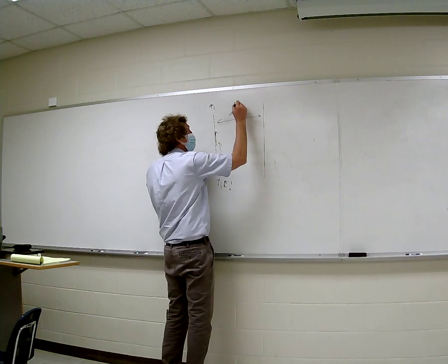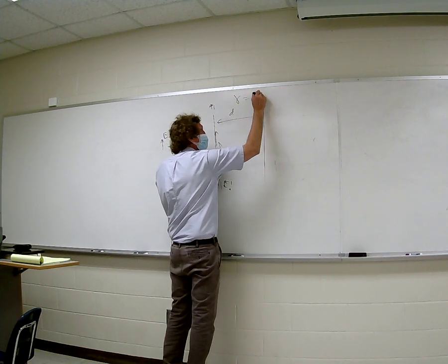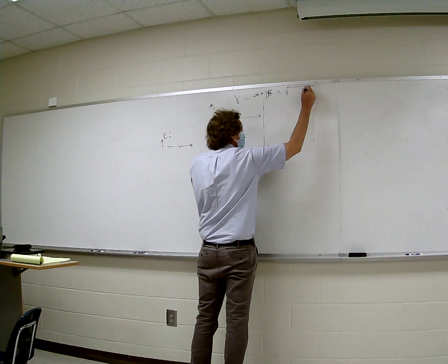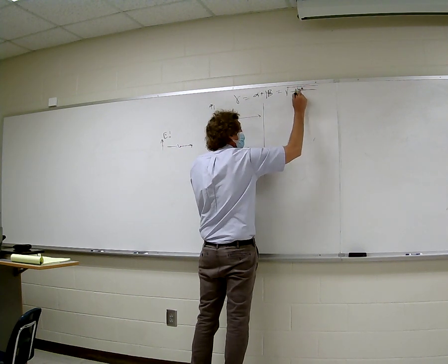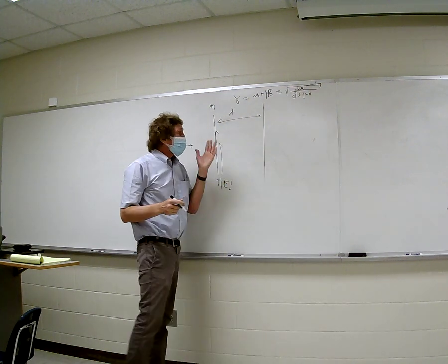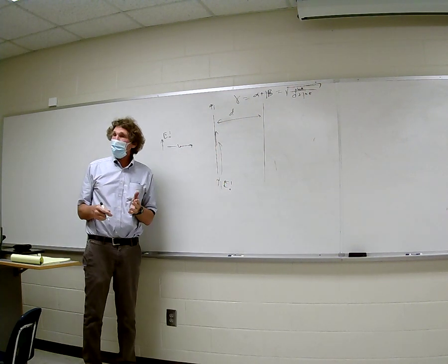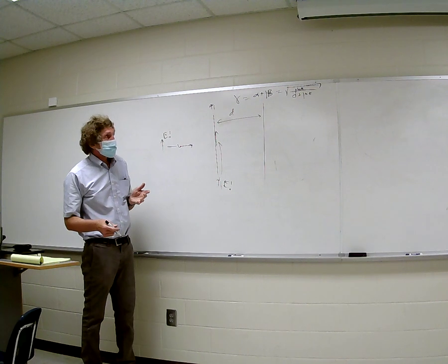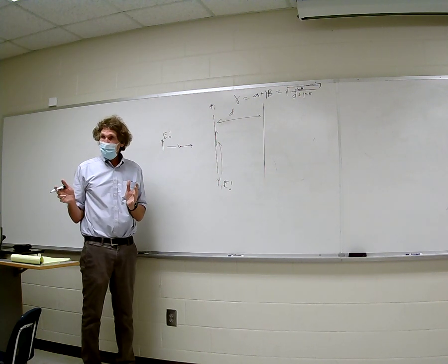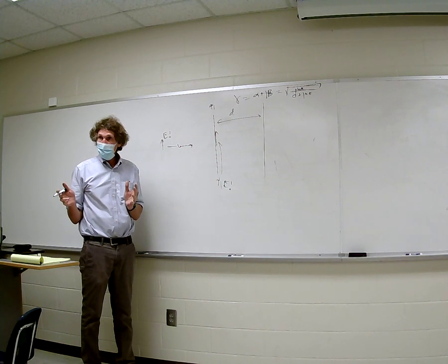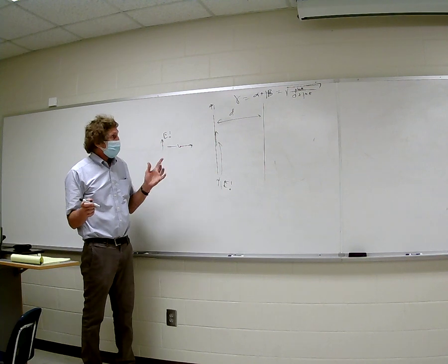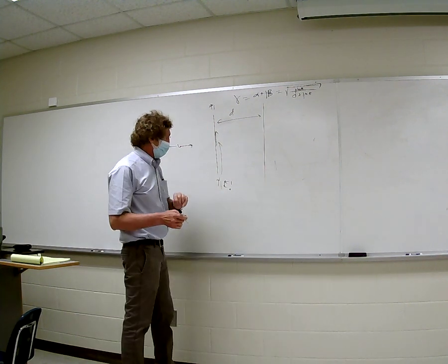And we know one thing about it. In here we're going to have some gamma that's alpha plus j beta, and that's equal to the square root of j omega mu over sigma plus j omega epsilon. If it's a good metal, if sigma's large, it's really about j omega mu sigma, right? Everybody okay with this? All right.